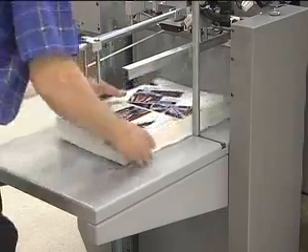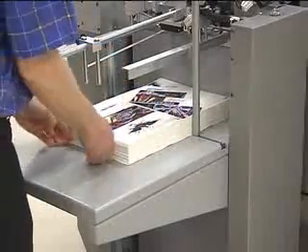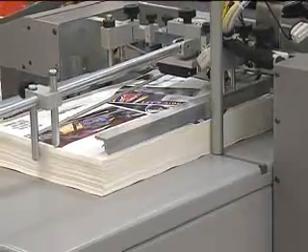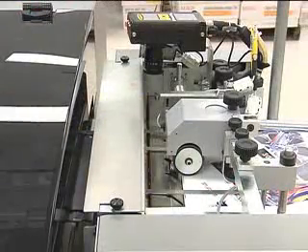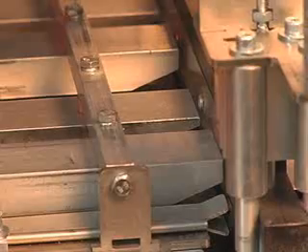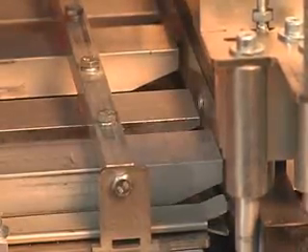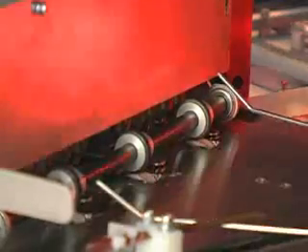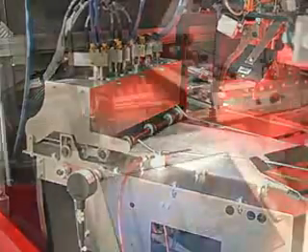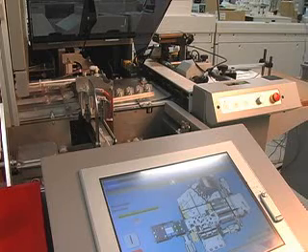The first step is to print the envelope sheets and inserts. Once completed, the pre-printed job is loaded onto the feeder platform. The K515 will feed one sheet at a time. Once the sheet is pulled off the sheet feeder, it will enter the K515 and, in the case of A3 or 11 by 17 inch sheets, stop so that the internal cutter can cut the sheet in half. The envelope sheet is flipped, glued, and sent to the folding station. Meanwhile, the first insert sheet will go to the front of the K515 to get Z-folded.